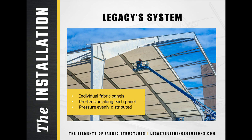In Legacy's patented attachment system, each fabric panel, typically 20 feet wide, is secured to the frame using a Keder attachment system. The most important advantage of any Keder system is that it evenly distributes the pressure created by wind, snow, and fabric tension to every frame, not just the end frames. The Legacy Keder rail system allows for greater pre-tension on the width of the panels, which means more horizontal tension and longer lifespan for each panel.